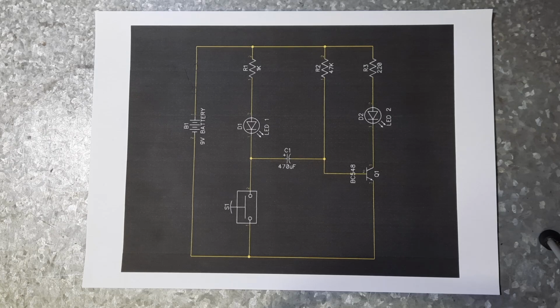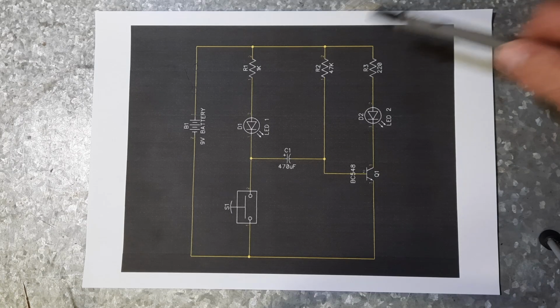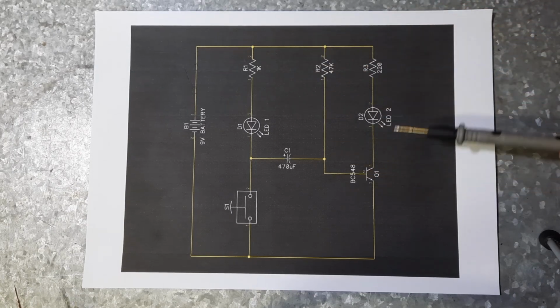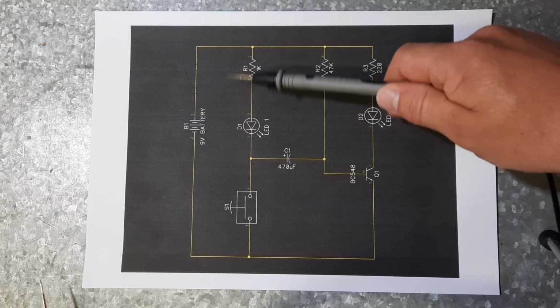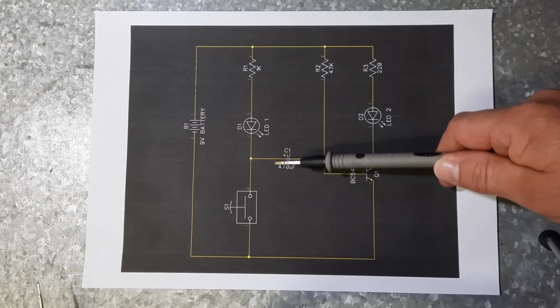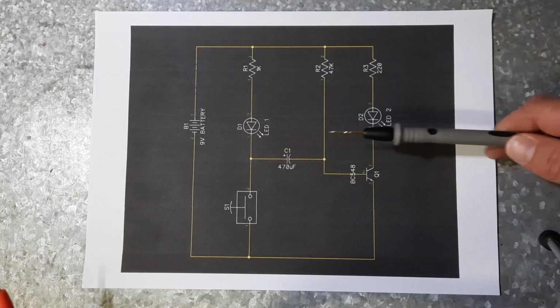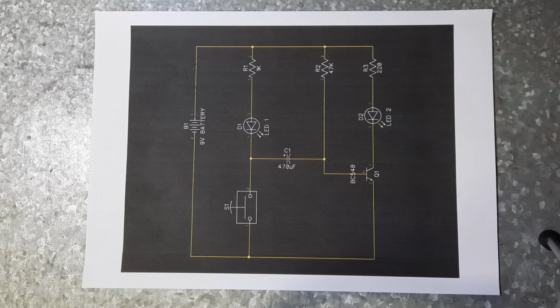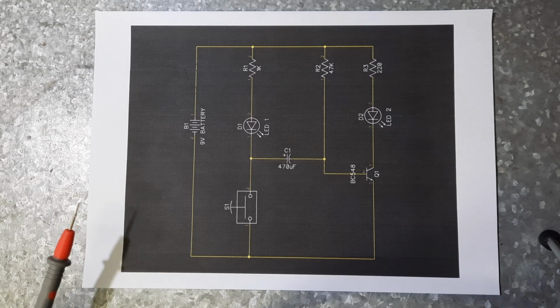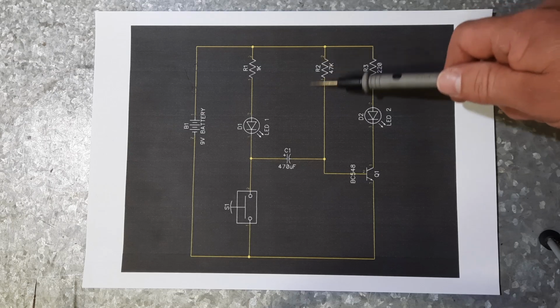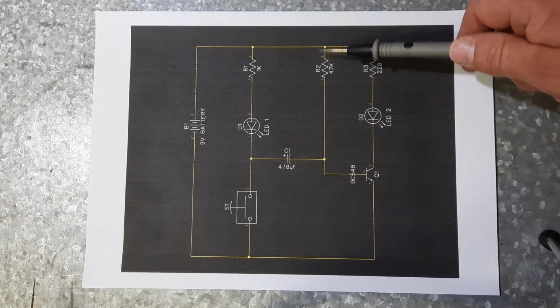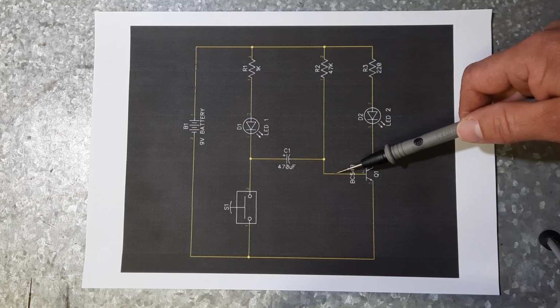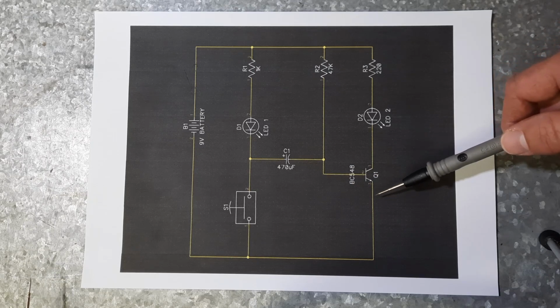When we apply power to this circuit, we know what's happening through this half of it. But what happens through here and this capacitor, it gets a little bit tricky to understand. But once you do understand it, the rest, how the circuit works, becomes a lot clearer. So we know that there's 2 volt drops in this leg of the circuit. One from here to here, and one from here, the base, to the emitter.